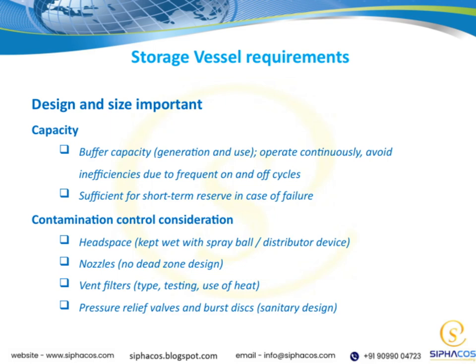Having sufficient buffer capacity also provides a short-term reserve in case of unexpected failures or disruptions, which adds an extra layer of safety and reliability. Now, when we look at contamination control, there are several design considerations to keep in mind. For example, headspace, the space above the material, should be kept wet using spray balls or distributor devices. This helps prevent contamination and buildup.